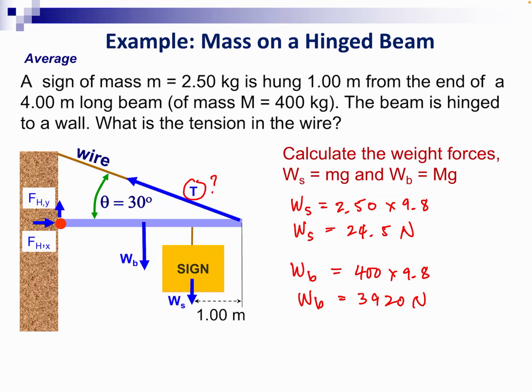So to do balancing of torques, we need to choose a pivot point. So pick a pivot. In this case, which will be the most sensible position to put the pivot at? Remember that the point where you put the pivot is the point where forces are eliminated. So you have 5 forces, but essentially you have 4 positions, 4 choices of where you can put the pivot point.